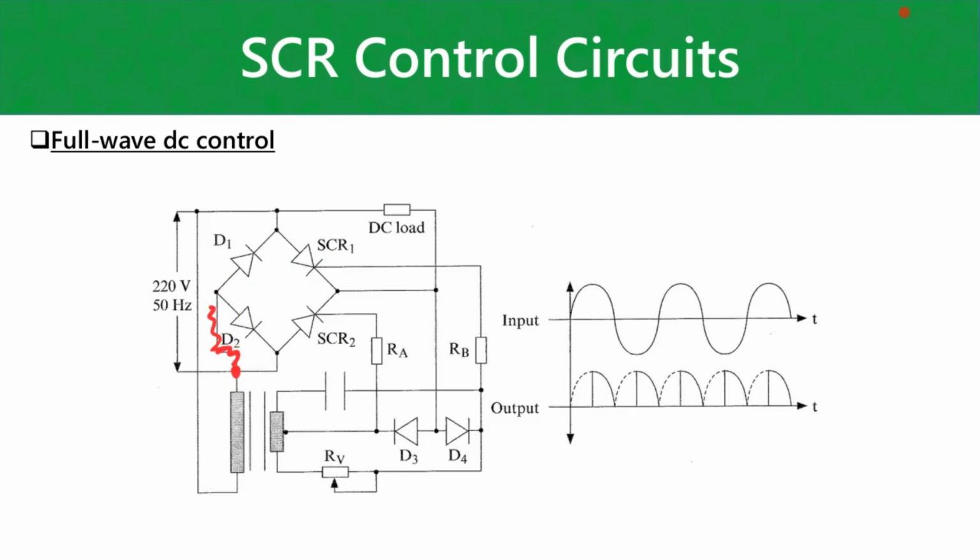That can be, let me maybe, I don't have white. Okay, so that line needs to come out. Our DC load here is also connected incorrectly. It shouldn't be connected there. In fact, your DC load needs to be connected to this corner here where the transformer is connected incorrectly. So that's how that should be connected. Then your circuit is correct.